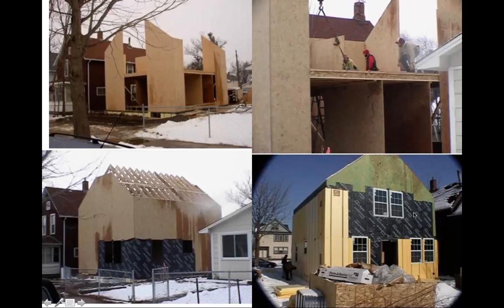That's basically your water resistant barrier. And on the outside of that comes your insulation, and then siding goes on top of all of that. So it's a different sort of system, potentially performs much better in terms of water management. But of course the challenge you have is this is a new system. So if it's a new system, how does it do with respect to supporting the loads and so forth?